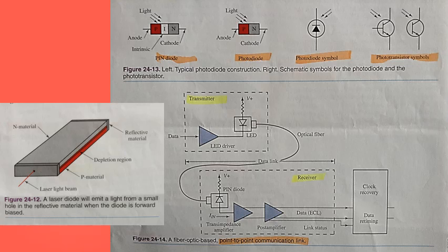In Chapter 17, Introduction to Semiconductors and Power Supplies, you became familiar, or you should have, with LEDs. So here we will look at the construction of a laser diode, figure 24-12. That is the left side of your screen. The construction of a semiconductor laser diode is simple. The laser diode is similar to a conventional diode. In construction, a P-type material and an N-type material are sandwiched together. A forward-biased diode emits radiation at its junction, or depletion region.